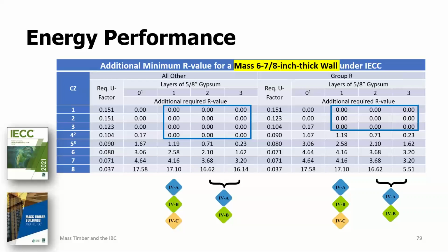So it becomes a trade-off. If you want to have a little bit extra panel and thus can have less or no insulation, depending on climate zone and whatnot, it's the cost of the panel versus the cost of having an extra trade go in there for the insulation.